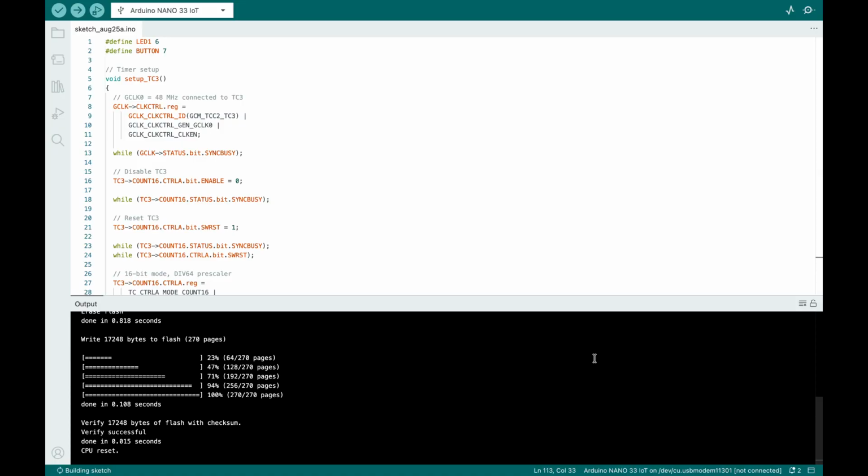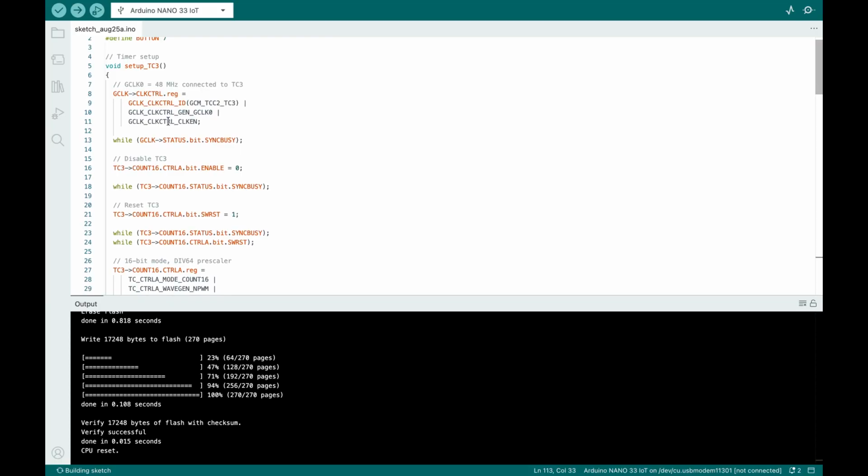For the hardware setup, I'll show you the hardware setup in the images at the end. But for now, I'm just using an Arduino Nano 33 IoT along with one LED that is connected to the digital pin D6, and the digital pin D7, which is connected to a button. I also use a resistor to connect the LED. Let's move on to the code.